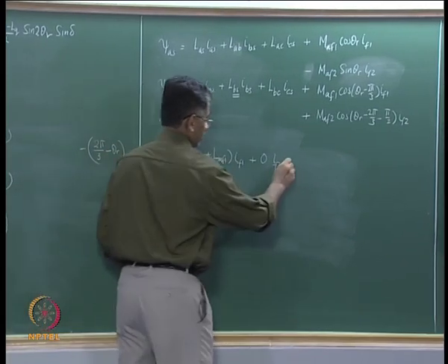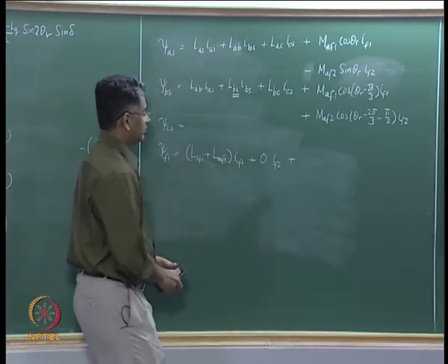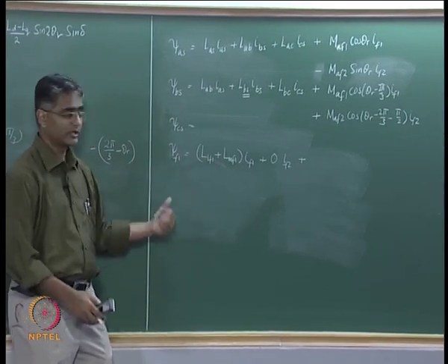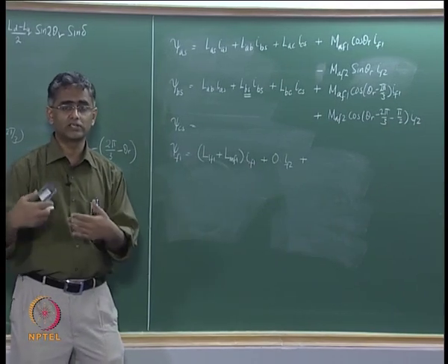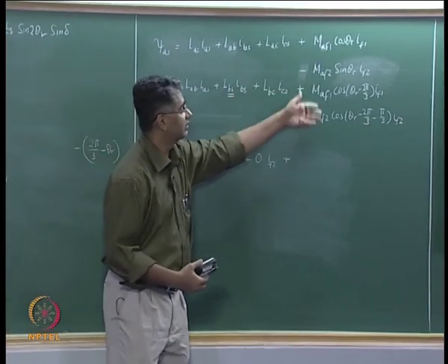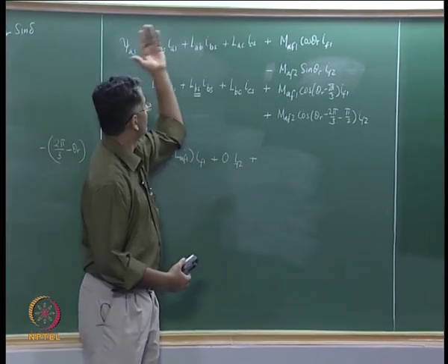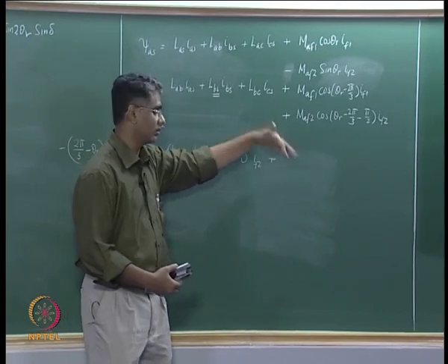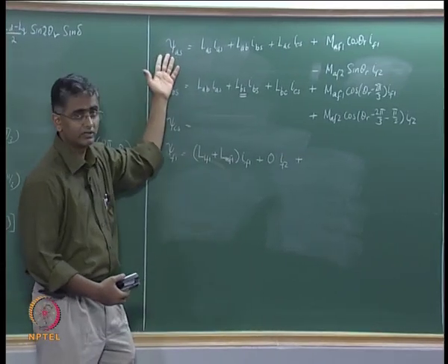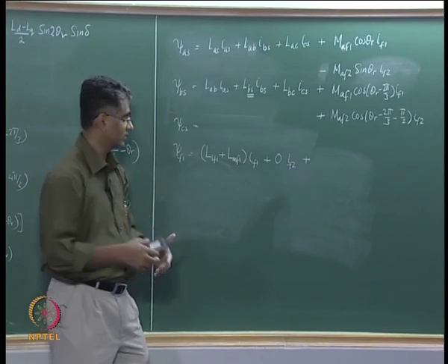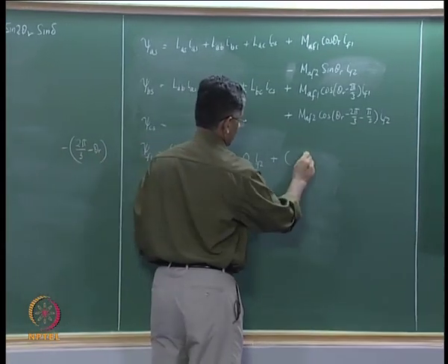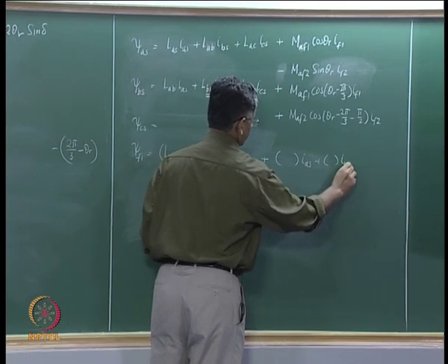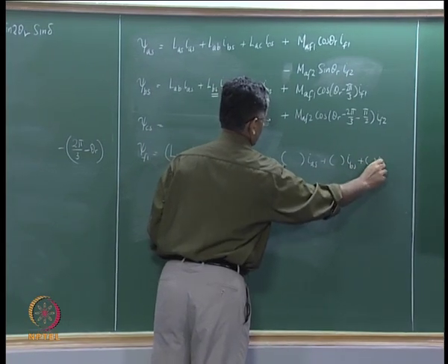And then you have the mutual flux linkages between the stator windings and F1, and those are described by the same mutual inductances that we have written here, whether it is between stator flux linkage caused due to current in the rotor or rotor flux linkage caused due to current in the stator, the mutual inductance term remains the same. Therefore similar mutual inductance terms would then arise.